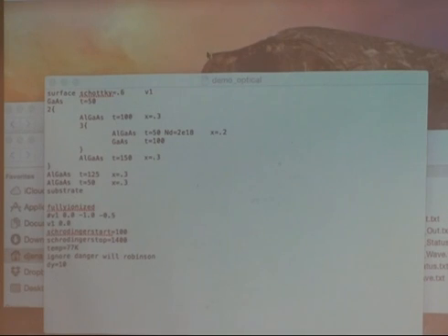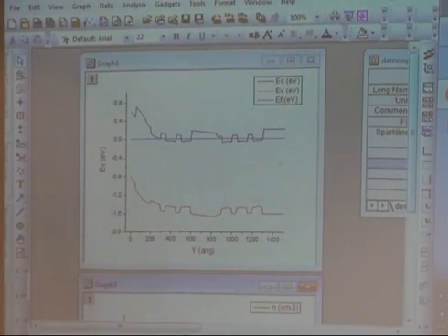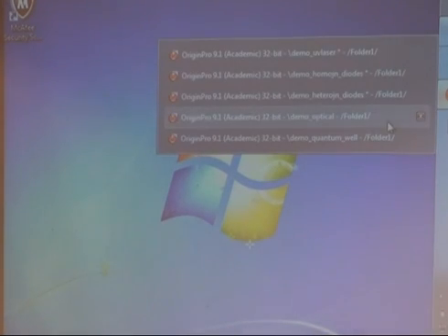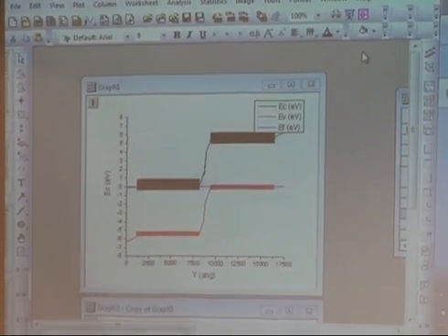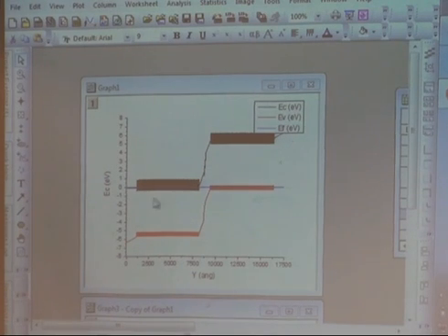I think we're out of time. So the last thing I would show is a real design. For example, in our group's research, we're trying to make these deep ultraviolet structures for light emission, lasers and all that. The band diagram starts looking very interesting. Here's a band diagram calculated with 1D Poisson. You have all these superlattices, quantum wells, active regions, a PN diode, but with a very large band gap. If you zoom in into a very small window here, this is a superlattice